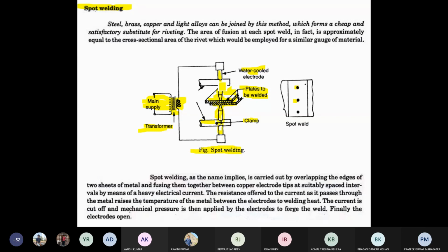at a certain voltage. So the medium breaks down, and a huge current flows inside the plates, from one electrode to the other electrode. So if the current is flowing between the two plates, they will be joined only at those positions, the pinpoint positions. Here you can see the top view after joining: the plates have joined together. It is a spot weld.